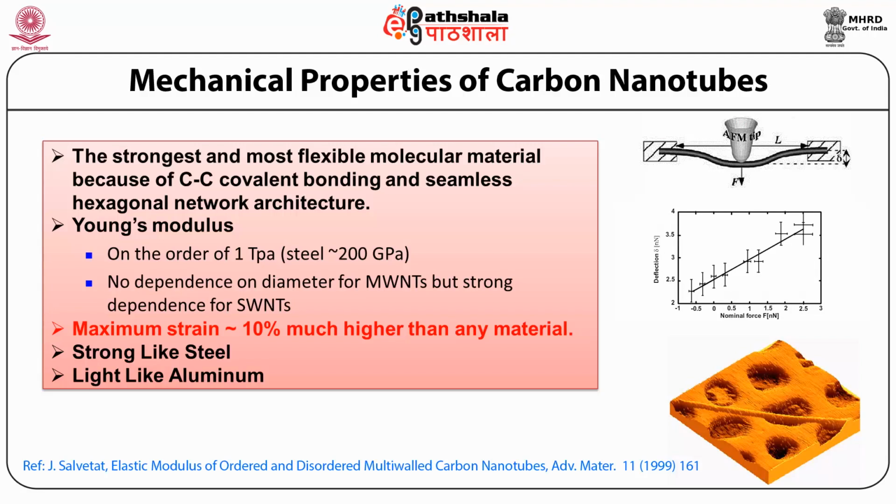In general, defect-free nanotubes are stronger than graphite. This is mainly because the axial component of sigma bonding is greatly increased when a graphite sheet is rolled over to form the seamless cylinder structure of SWNT. Young modulus is independent of tube chirality but depends on the tube diameter. An experimental study for calculating the mechanical strength of CNT is shown in the figure.